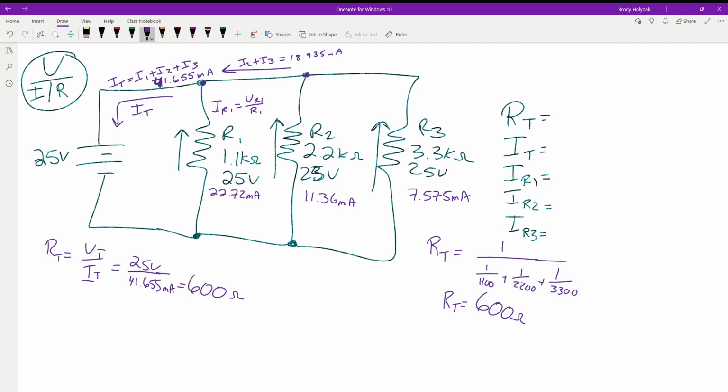Remember the difference too is when we're in class, we're talking about theoreticals. So the values we use are usually spot on. When you get into lab, your 1.1K is not going to be 1.1K. It's going to be 1.0K, 1.02K, things like that. Use those values that you actually measured when you're doing your calculations for lab. Because the difference is theory and lab. Theory is perfect world. Lab is application of perfect world principles in an imperfect environment. So you have to account for those losses and differences, and when you do, your measurements will line right up.